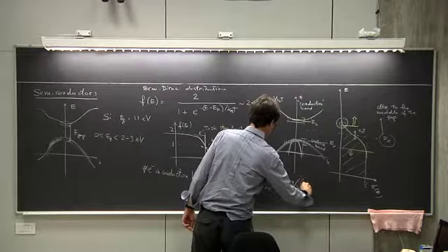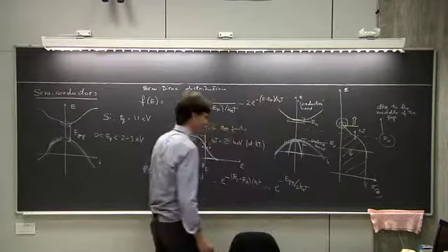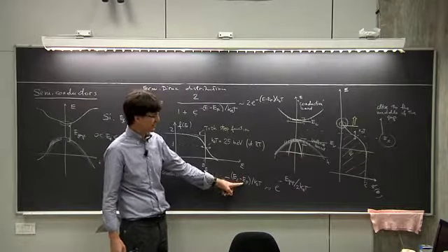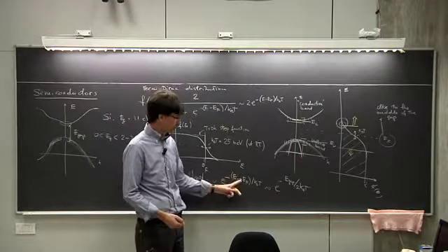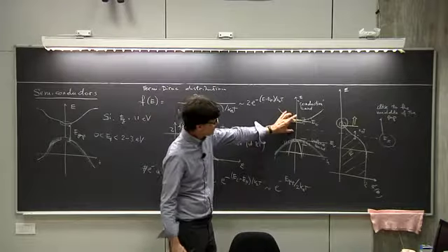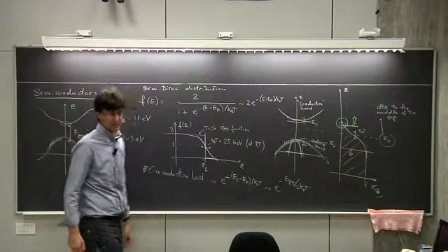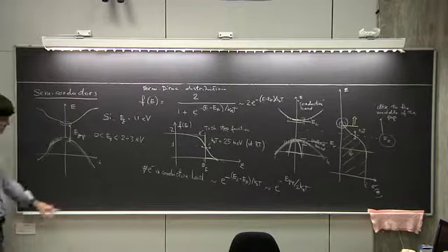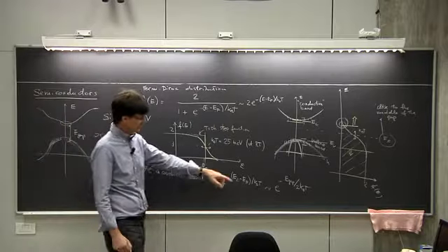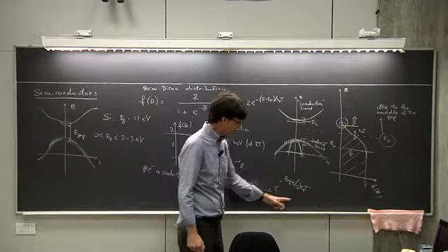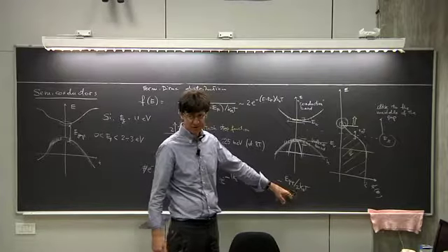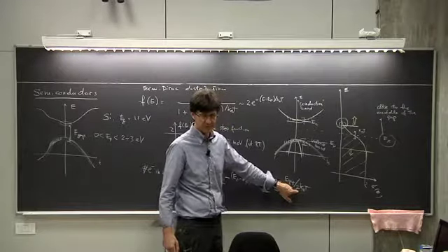Two kBT, approximately, right? Because I know that the Fermi energy is roughly in the middle. So the difference between the conduction band and the Fermi level is approximately 1/2 of the band gap. So the result is that the number of electrons in the conduction band takes this interesting value, which is, I mean, similar to Boltzmann, but it's not really Boltzmann because there's a factor of 2 here.